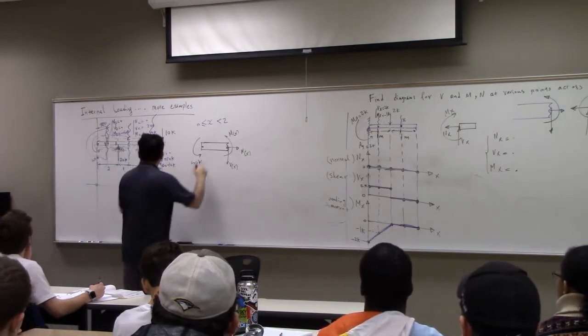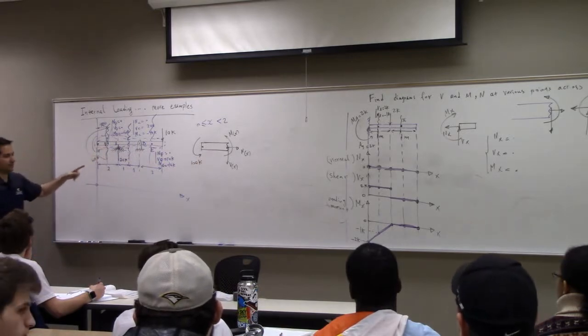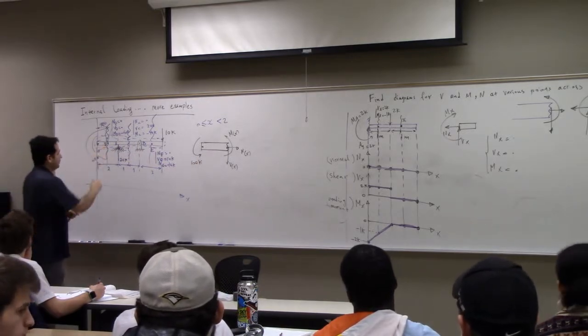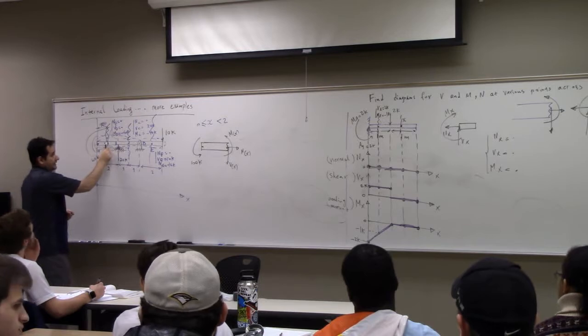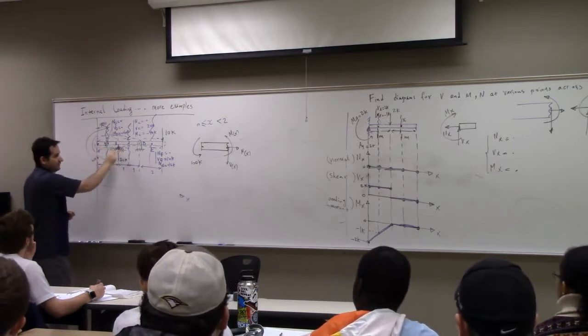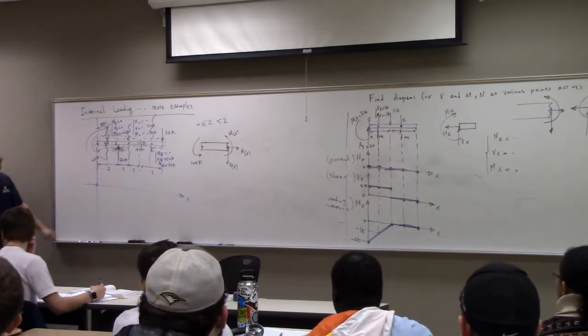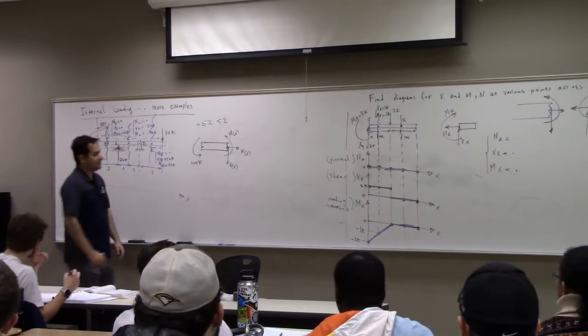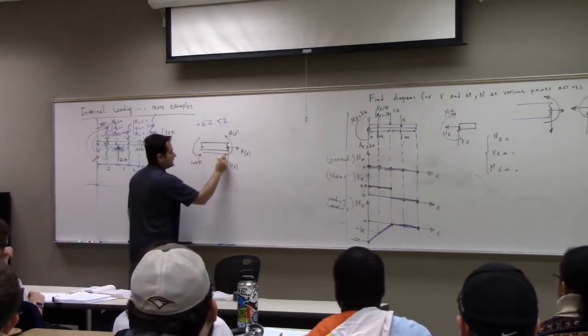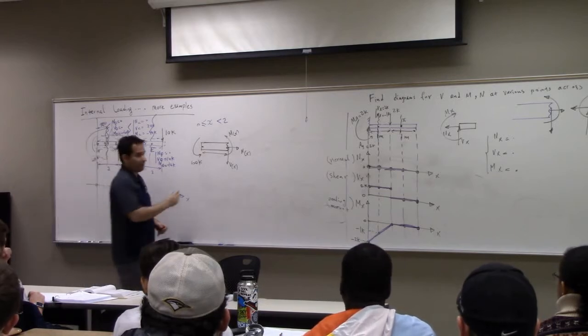So now this is my FBD, with the 60K, Nx, Vx, and Mx. And don't forget again one more time, the x is not exactly at 1. It could be anywhere in this range. Then what is from here to here? The length of this part of the beam. What is the length of this part of the beam? Just x. Don't forget that.